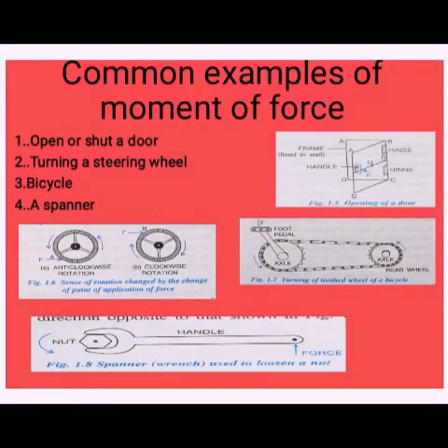Common examples of moment of force. To open or shut a door, we apply a force F normal to the door at its handle P, which is provided at the maximum distance, as you can see in picture 1.5. If we apply the force at the point Q, that much force is required to open the door. If the force is applied at the hinges, we will not be able to open the door itself.